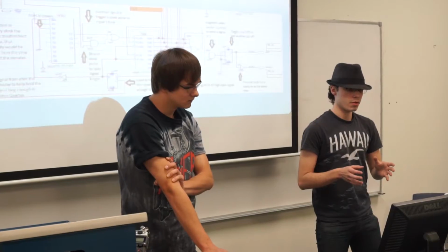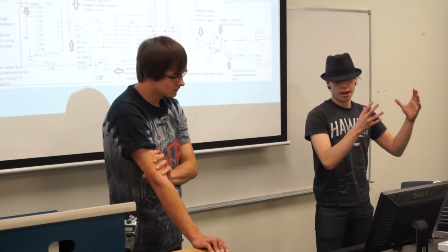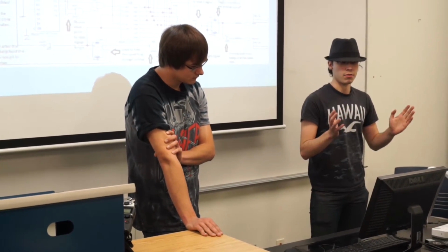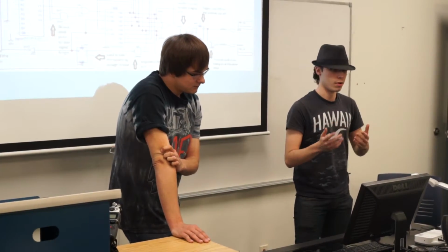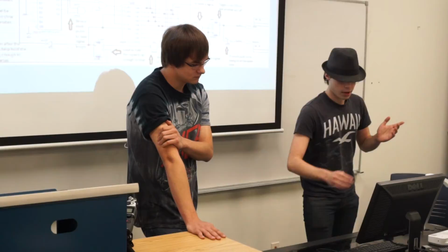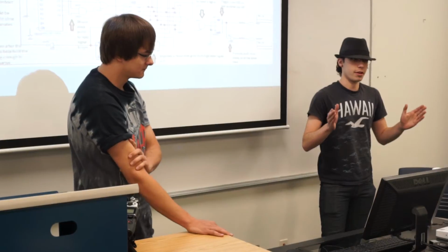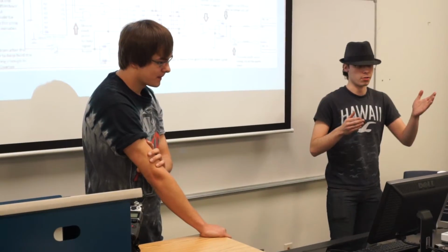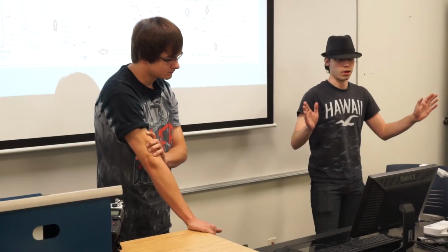As we encountered with this program itself, everything else had been tested by itself and later added together, and they all worked fine, but every time we added the hours in, we were having an odd issue of Quartus not registering our value signals coming in. That is quite literally why our D flip-flop is right here, because Quartus was running a subprogram that was preventing us from having our clear signal on long enough to clear the function at all. So it was going to 99 even though it was programmed to go to 0 after reaching 12.